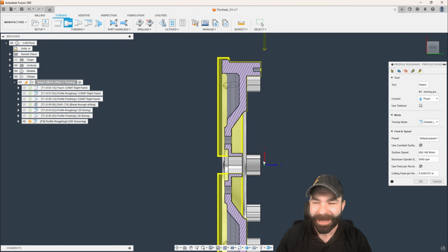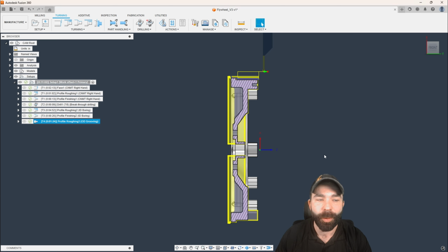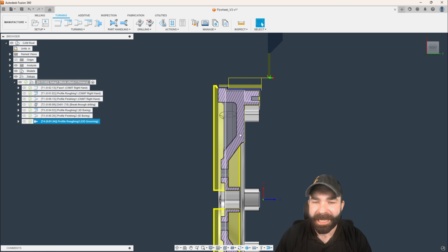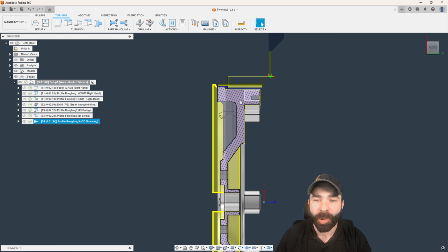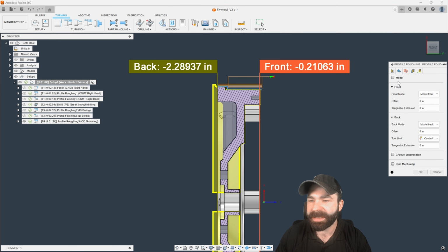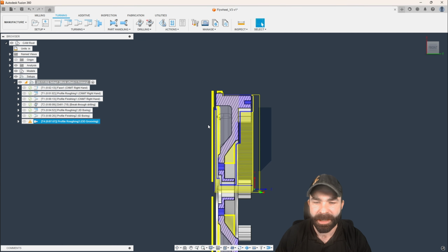But again, let's go ahead and grab that lollipop cutter. We are working on this part, so I'm going to go ahead and hit OK with its standard settings because I don't know quite how it's going to react, right? So we did say just use a grooving tool, however, use it as adaptive clearing. And as you can see now, we're doing our OD work, right? Well, let's start by switching from OD work to ID work, right? So again, as we're going to go from outside to inside, I'm going to hit OK.